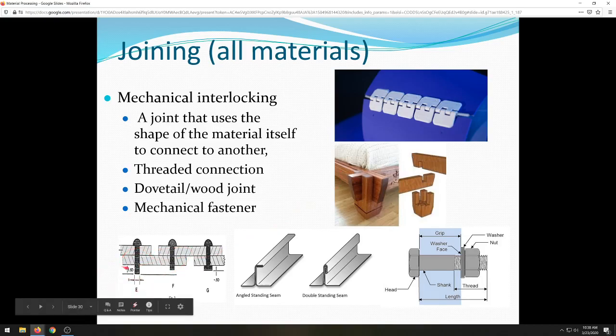Here we've got a rivet. Very common, used to be even more common right around the turn of the century, 1800s, 1900s, for building. But basically you take your two pieces of material, one end is pre-mushroomed on the rivet, and then you mushroom the other end over, so that there's no way they can come undone. So imagine if you did a grid of these, like 9 of them, in a 3x3 grid, you'd have a very strong connection because you're pulling and squeezing the material together, and there's no way that it can come out or come loose unless it breaks.